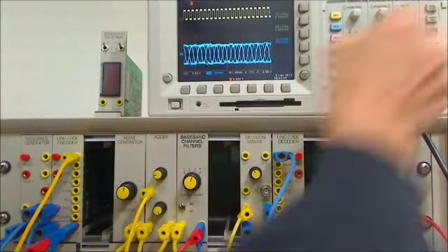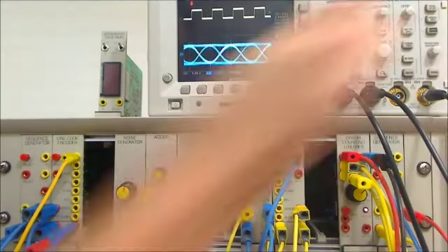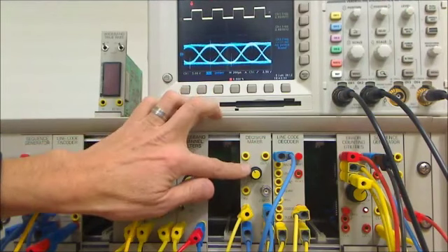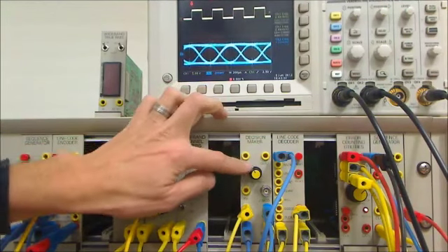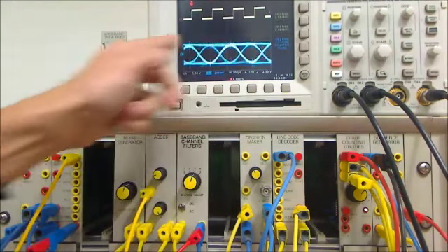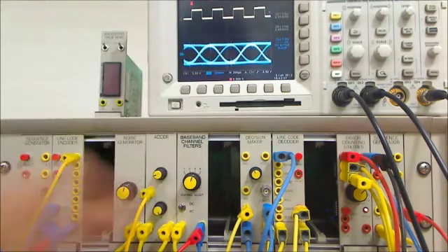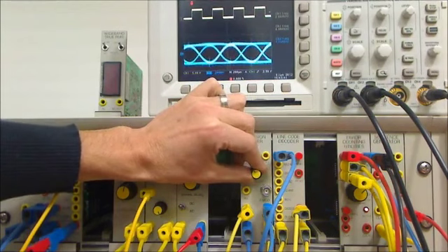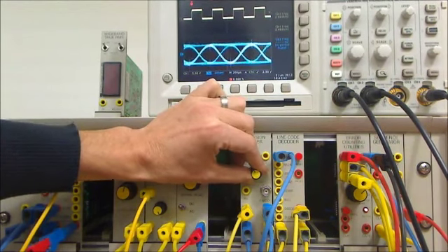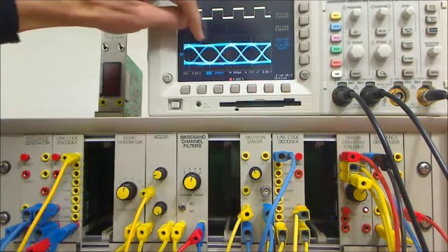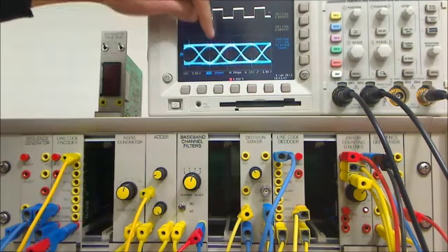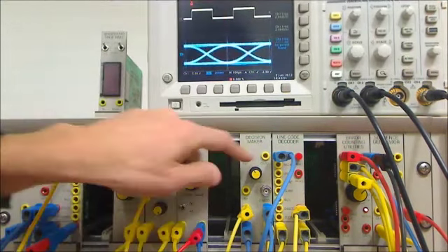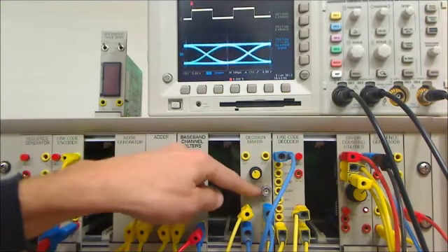For now, we'll concentrate on viewing the signal as an eye diagram. The decision maker has the very useful feature of being able to vary the decision point across the eye. So the issue is, when we move the decision point across the eye, we want to choose the optimum point, which happens to be in the middle. So how do we know where the decision point is?